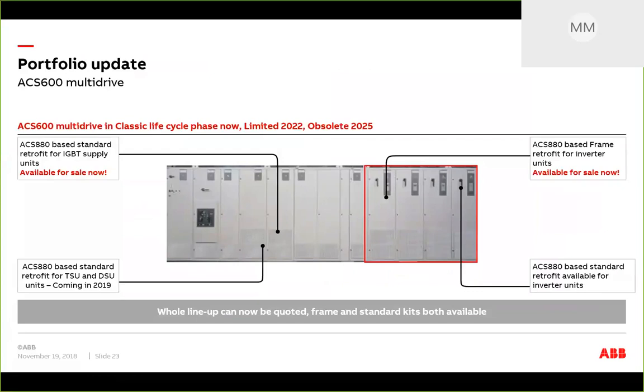It's designed to gut the old one and put the frame in, and with some software modifications to the program that could be done ahead of time, and maybe some small changes to the overriding controller, we could retrofit either a couple of single sections during an outage, or an entire lineup during an extended outage. So that would be one way of retrofitting as part of this implementation process.